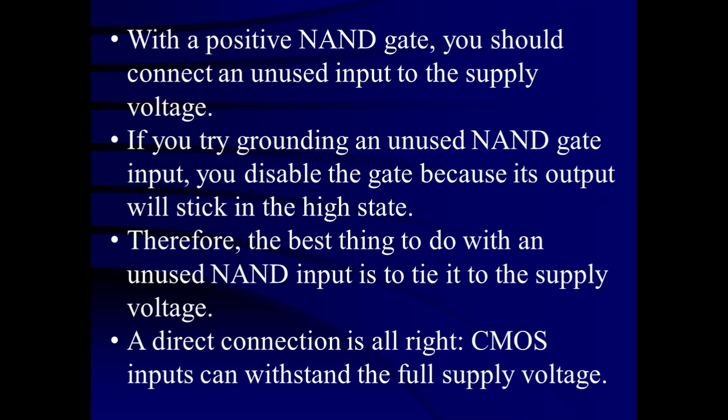A CMOS input can withstand the full supply voltage. That means when it is connected to the supply voltage, you don't require a pull-up resistor like in TTL, because it can withstand the full supply voltage even if that supply voltage is 15 volts.